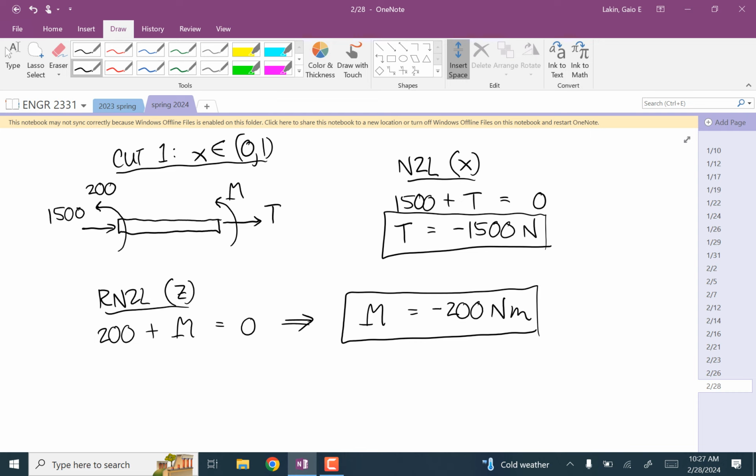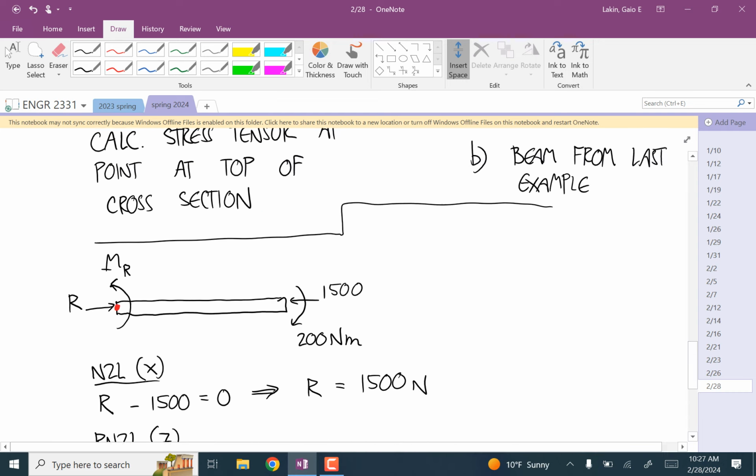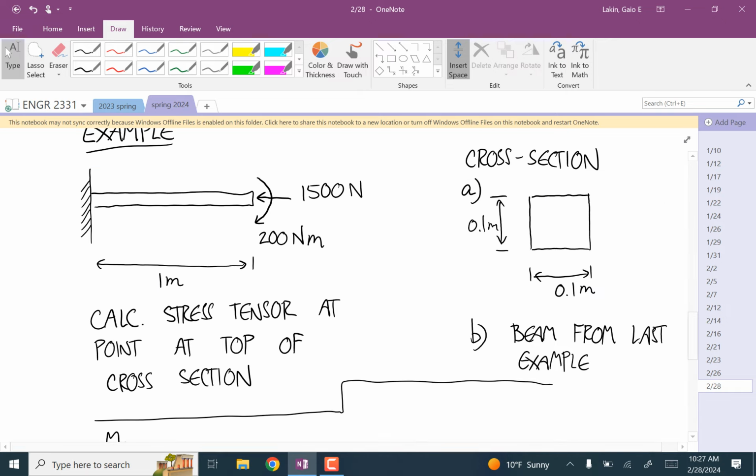Okay. Remember St. Venant's principle, like if somebody asked you to calculate the stress right at this endpoint, you'd want to be careful about that, because if it's applied as a point force, there'd be weird deformations or whatever close to the end point. But once you get into the body of the thing, away from the two ends, these answers will be accurate.